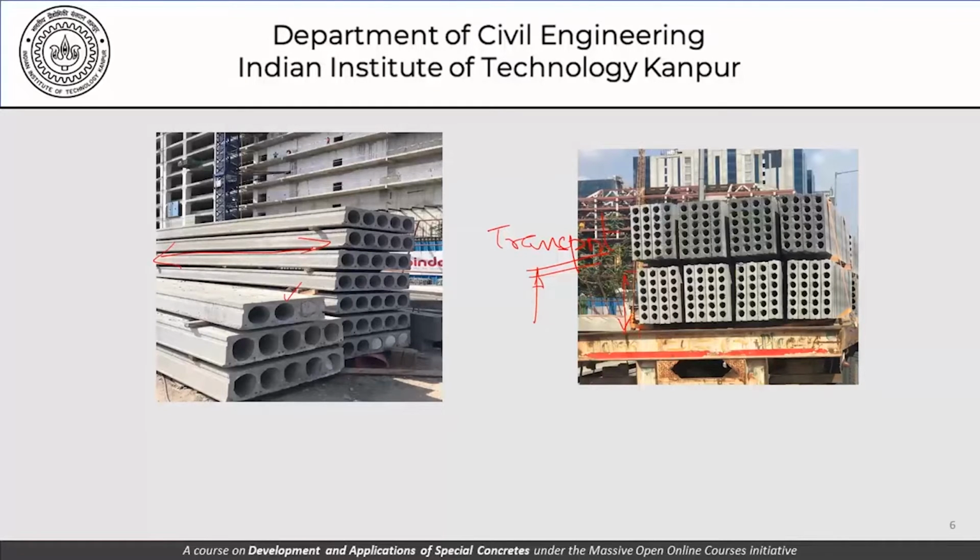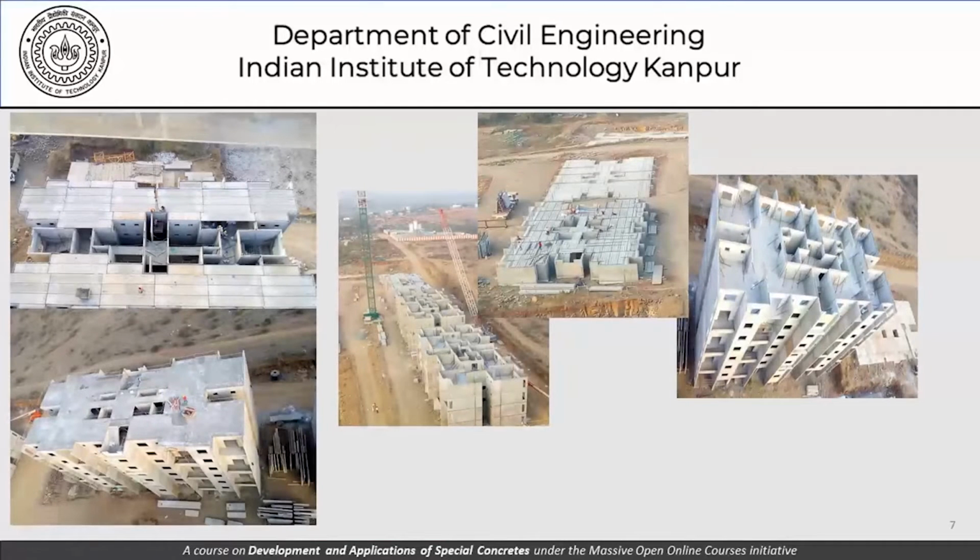Why do we do a lot of precasting? Because it adds speed. It not only adds speed to the construction, but also it helps us in quality control, because these members, once they are created in a factory environment, it's easier to control the quality in the factory environment than at site. At site, if we have less construction being carried out, there's less pollution, less need to store material there, so we can possibly do precast construction in a smaller site where there is no space to store and stack the construction material.